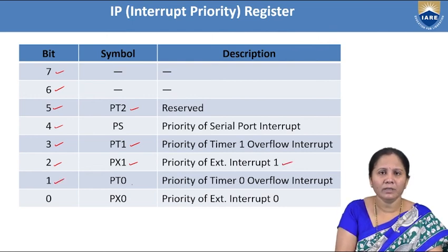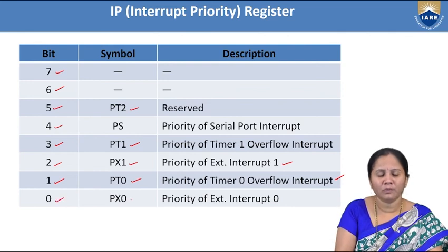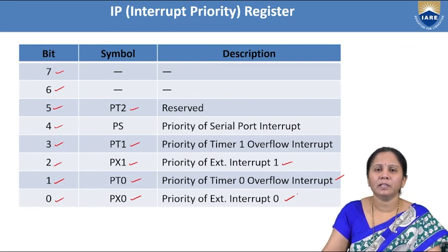And the next bit is bit 1, that is PT0. It shows the priority of the timer 0 overflow interrupt. And the next one is bit 0, which is PX0. It shows the priority of external interrupt 0.